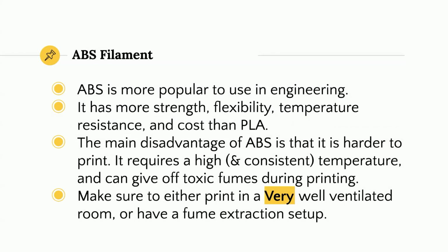ABS filament. ABS is more popular to use in engineering. The reason why is it has more strength, flexibility, temperature resistance, and cost than PLA. Essentially, when I say cost, I more so mean it's cheaper. The main disadvantage of ABS is that it's harder to print.